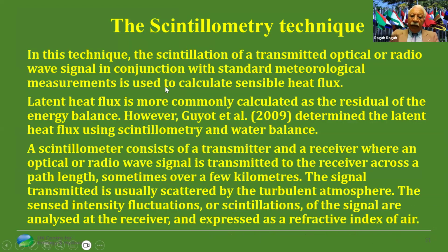This is a technique where the scintillation of a transmitted optical or radio wave signal, in conjunction with standard meteorological measurements, is used to calculate the sensible heat flux. Latent heat flux is more commonly calculated as the residual of the energy balance. However, some scientists managed to get the latent heat also obtained from scintillometers with knowledge of the water balance. A scintillometer consists of a transmitter and a receiver, where an optical or radio wave signal is transmitted to the receiver across paths, sometimes over a few kilometers.